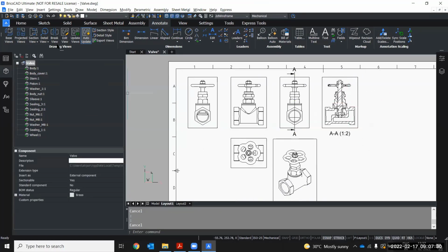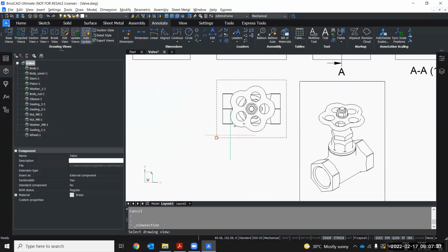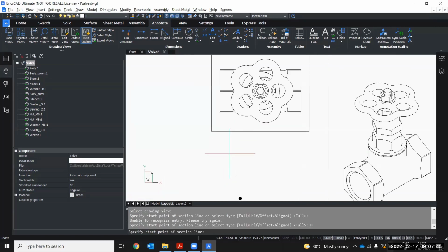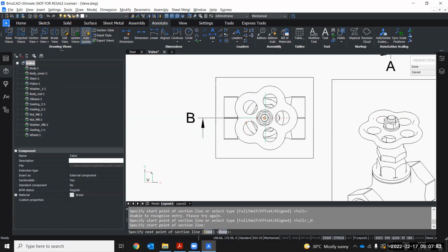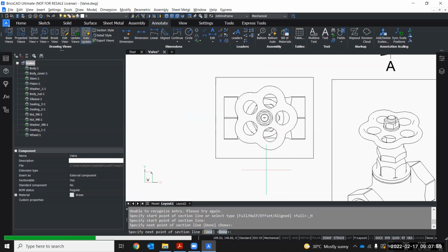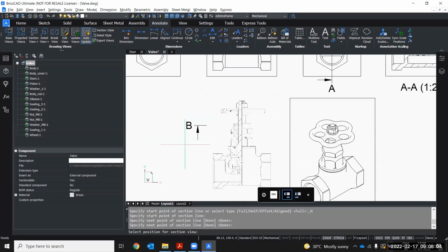You can also create a half section view. So just select that particular option and let's create a half section view for the bottom view that we have over here. So first of all, I need to select the view for which I'm creating the half section view, and I can snap to the center and go across. So I'll be starting from over here, right? And I'll select the midpoint. So I want to create a section up until this particular point, and then drag it downwards so that I'll be creating a view for this particular quarter section of the wall.